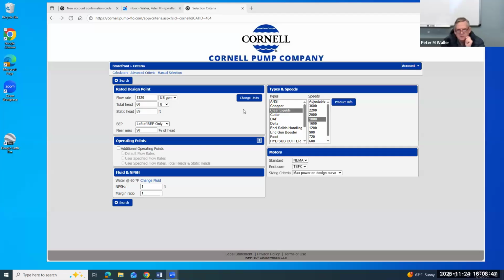Okay, so I signed into the Cornell Pump Company, which was my favorite pump. Actually, everybody's favorite pump 40 years ago. Not sure if they still are everybody's favorite pump. But I put in my flow rate, 1,320 gallons per minute. My total head is 60. I didn't know what static head meant exactly, so I put 59. This is a left or right angled pump. I said left. I didn't know what near miss meant, 90% of head.